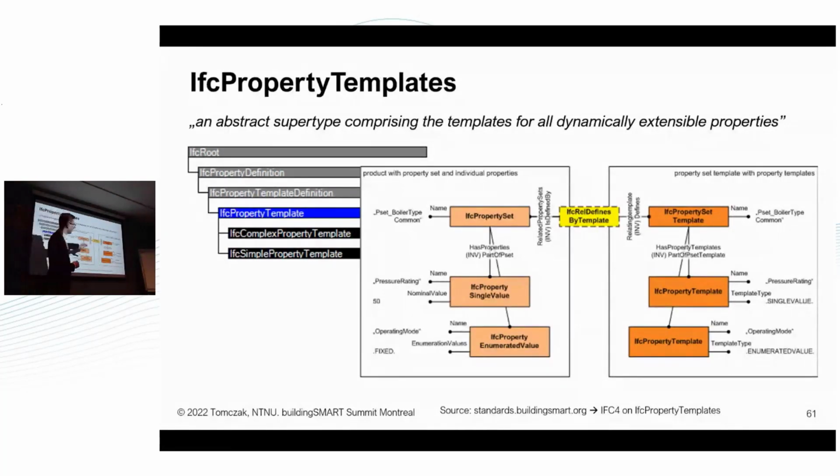And they are like a template to define what information should be for each class of objects. So then, using them, you can populate your property sets when you define your model view definition or your IFC data structure. But actually, I hadn't heard of that before I really dived deep into it and asked some experts, so I wasn't familiar with that before.